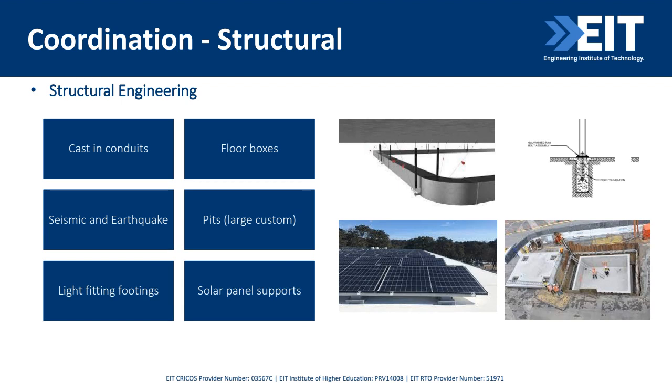Some other ones to run through. Maybe we're casting in conduits into their structure, so into the slab and the ground. That could be for something such as a floor box. We simply take a conduit to it. If you live or are doing a project in an earthquake area, you might have to design seismic restraints. Now what they are is, you can see them here. Imagine this is ductwork. It could be cable tray. And you have all of these lateral supporting wires that prevents that from falling down in an earthquake. That needs to be done by a structural engineer.